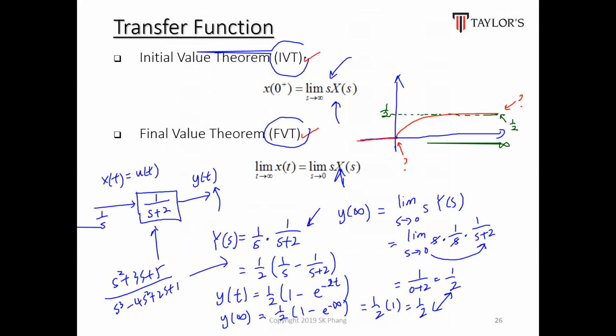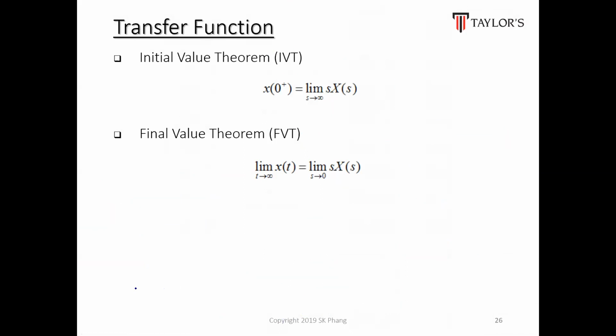Yes. For this initial and final value theorem, is it applicable for input and output? Applicable for any signal actually. So let me try with another signal. Let's say I have a signal that is u(t). You remember u(t) goes up, so the final value is always 1. The initial value is 0, but actually you cannot find the initial value here because at 0 it goes to 1.